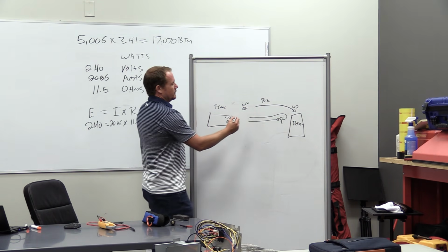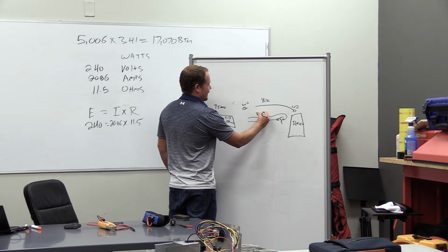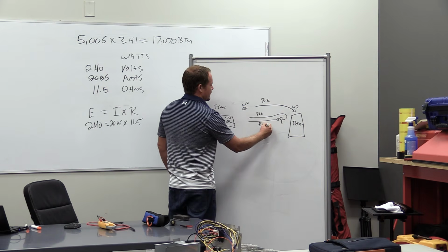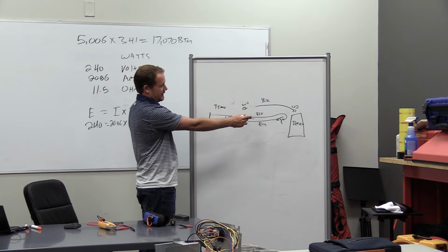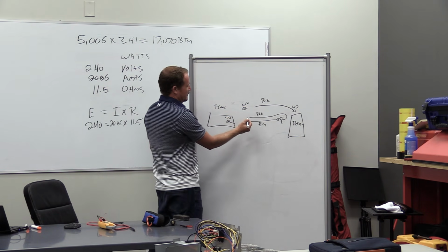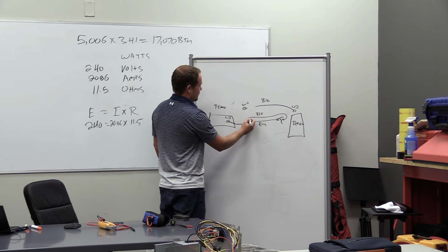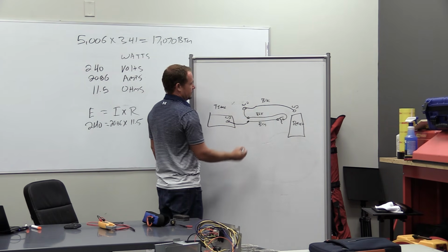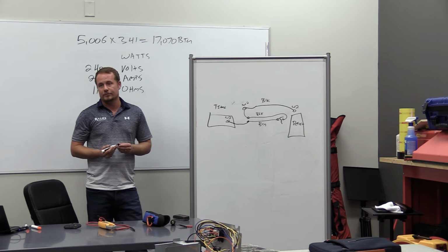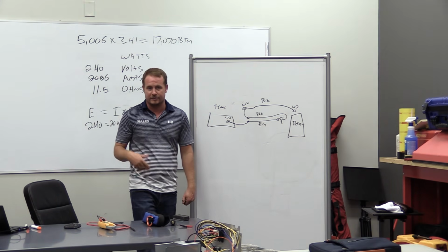would be to take two wires from the outside, and then you would go in here, still be off the thermostat, and you would go here, like that. But now you have to use two separate wires from inside to outside, so it's just a waste of an extra wire.